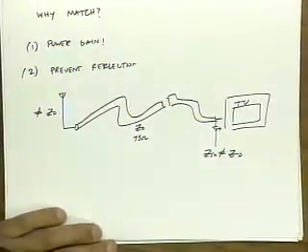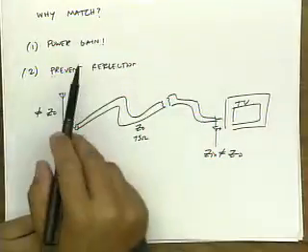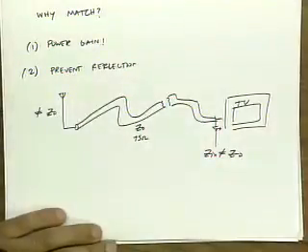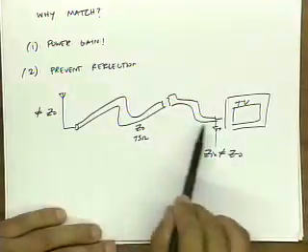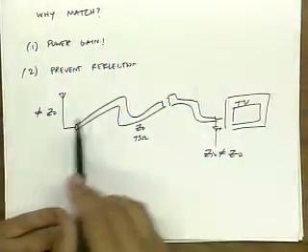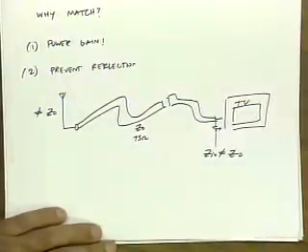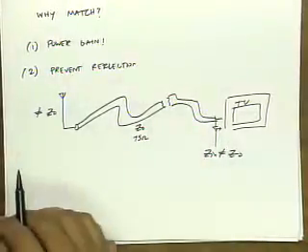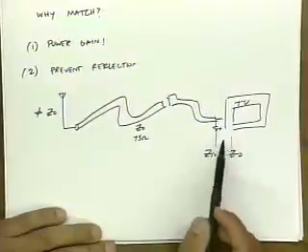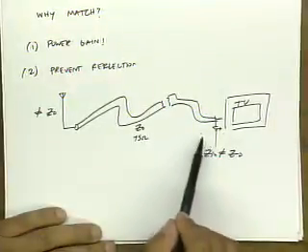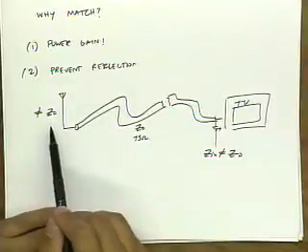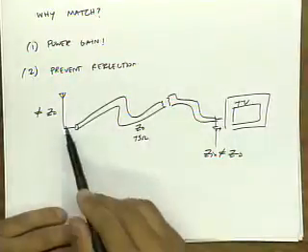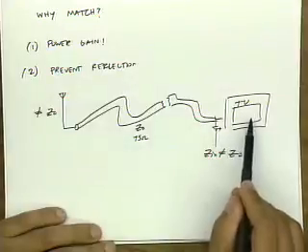What's the big deal? Well, the big deal, first of all, is you're not going to transfer the maximum power. That we've already talked about. But the other problem is that you're going to get reflections. The reason you don't get maximum power is that power is reflected from this television. And this is something we study in 117 when we study transmission lines. And this reflected power is going to come back to the antenna, and if the antenna is also mismatched, it's going to reflect again.